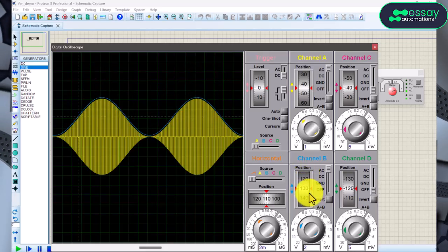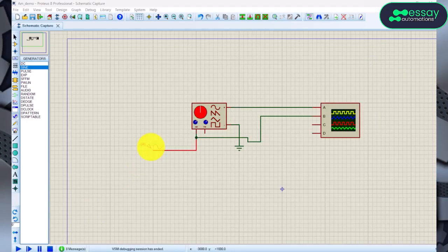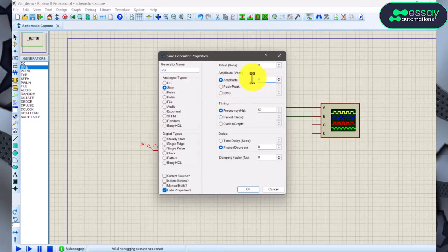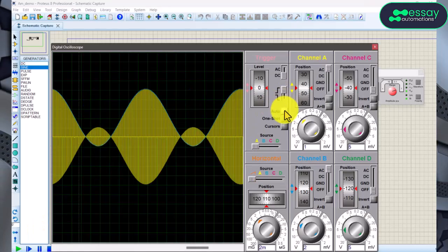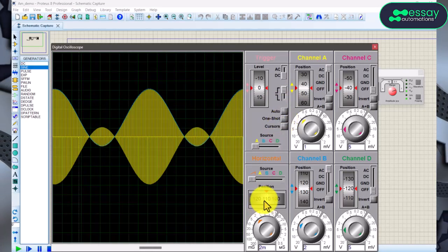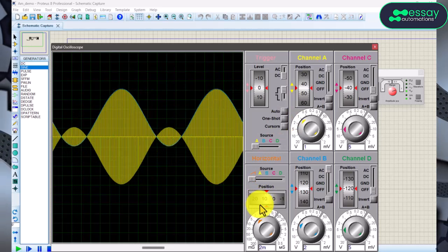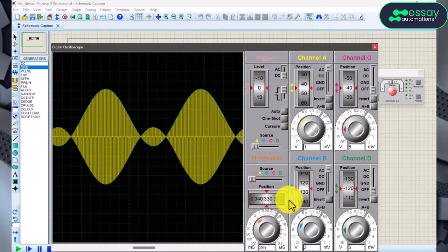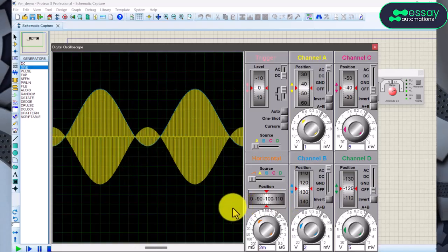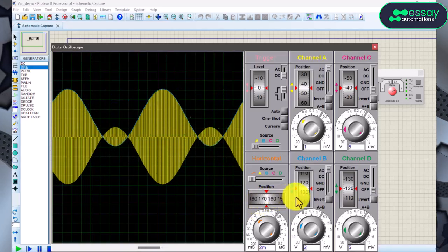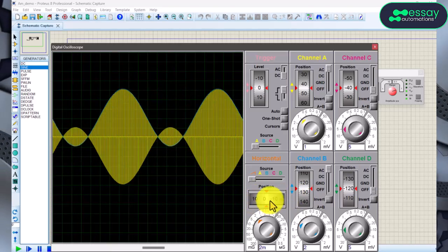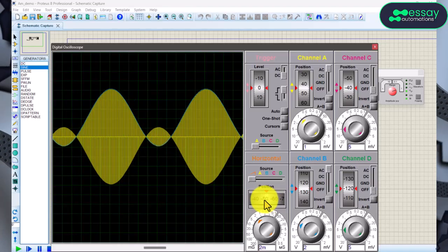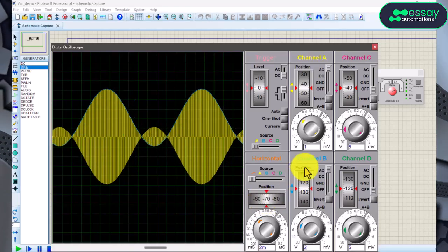Okay, and then let's overmodulate. So let's once again increase our information signal to, let's say, 6 volts, and then we have triplets form, like snapshots. Okay, triplets forming an inverted form of the waveform in between, and this characterizes over modulation, more than 100%. So there is one of the easy ways to use Proteus to